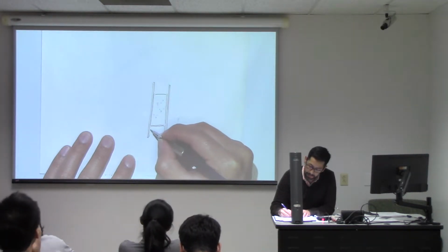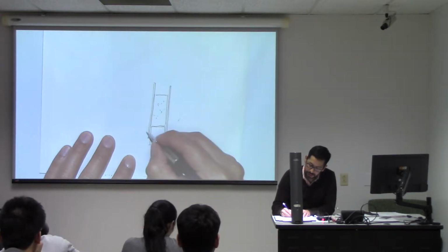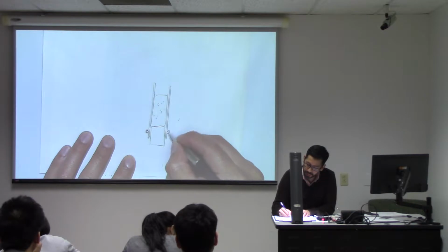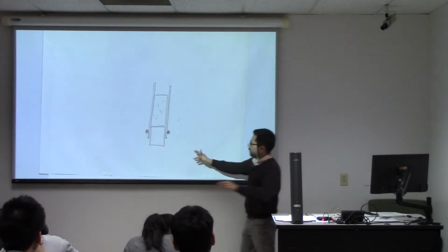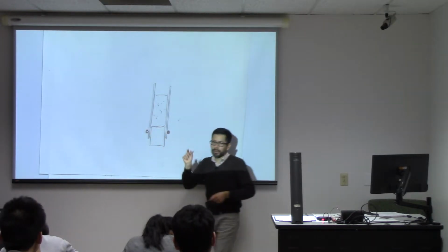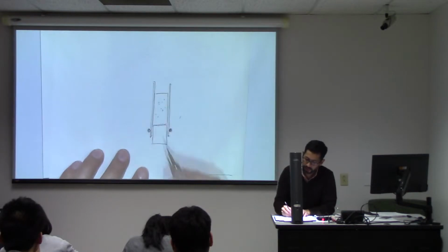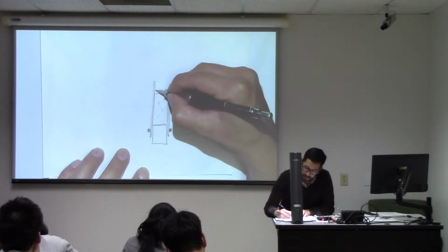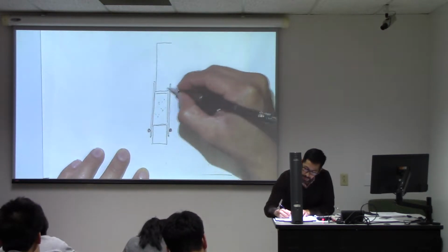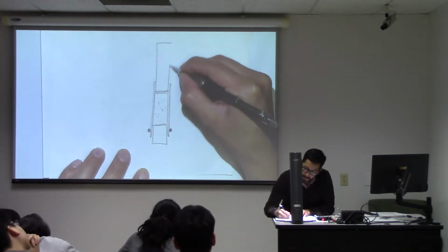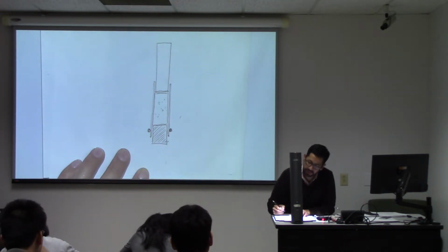You put an end cap here. Sometimes here you want to put an O-ring or some sort of material that makes these two parts very tight, so that there is no exchange of fluids between the confining fluid and the pore pressure fluid. This is usually steel or something very stiff.